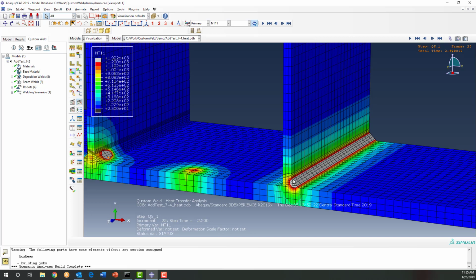So it pulses that energy over a short period of time, and then the rest of the time it just cools down before it goes to the next bead. So this is what we mean by chunking. So sometimes this is very useful if you have a model like this in some ways that's an extruded model. You can do this chunking and it can get very good results in most of the section of the bead.